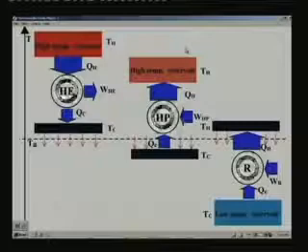In a typical steam power plant, the high temperature reservoir is the boiler of the power plant, and the low temperature reservoir is the condenser. Ultimately the heat from the condenser is rejected to the ambient. So here TA shows the ambient temperature. So the condenser temperature should be slightly higher than the ambient temperature, so heat can ultimately be lost to the ambient. So it is a cyclic device, so that is what the rotation shows.